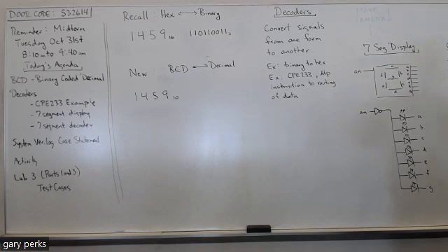Like I said, we're going to talk about decoders, and I'm going to start you with the code that you need in order to model the decoder in lab 3 with System Verilog. Then you'll have to connect the modules all together. You'll need a file in the same format as the RCA. Remember, the RCA connected the half adder and full adders into an adding circuit.